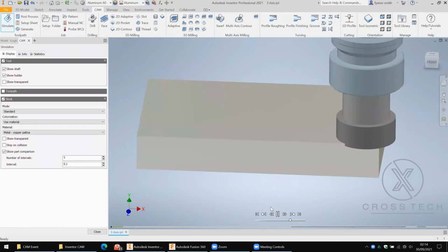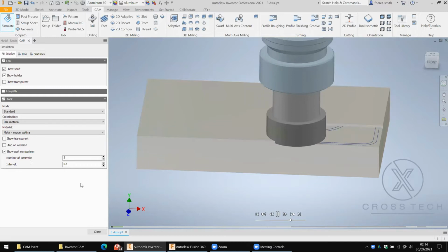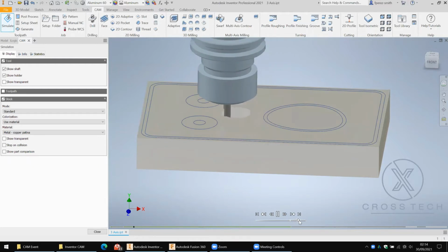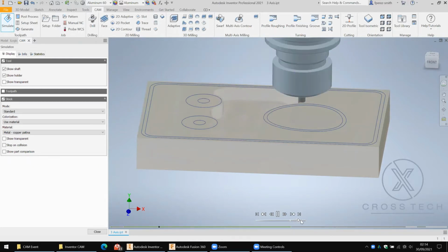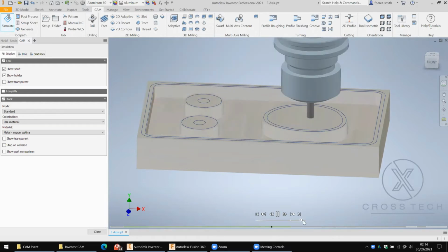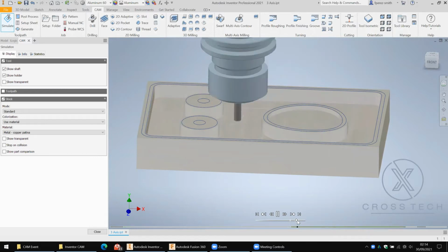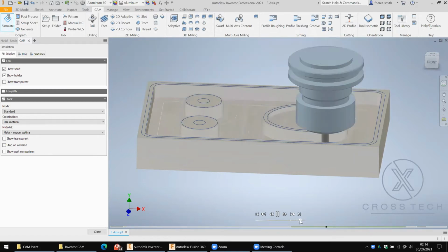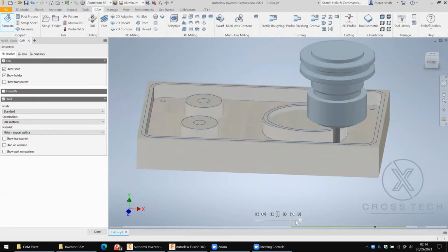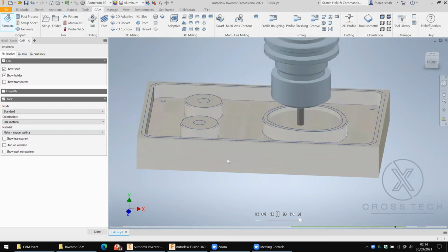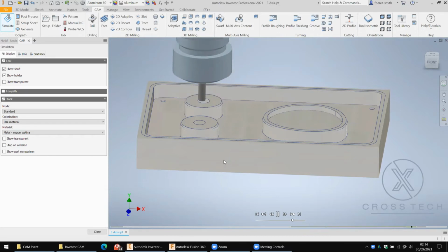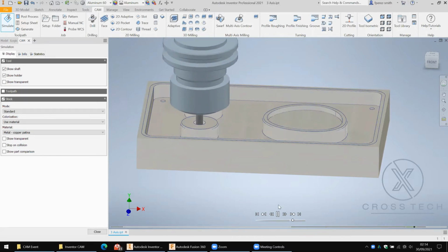And we begin with a big facing tool that will remove the top material. A roughing operation with the 2D adaptive, followed by pocketing operation for finishing. And I'll slow it down a little bit here. Now we've got the boring operations coming in, in which case the flat mill will come in a spiral pattern and bore out those two holes.